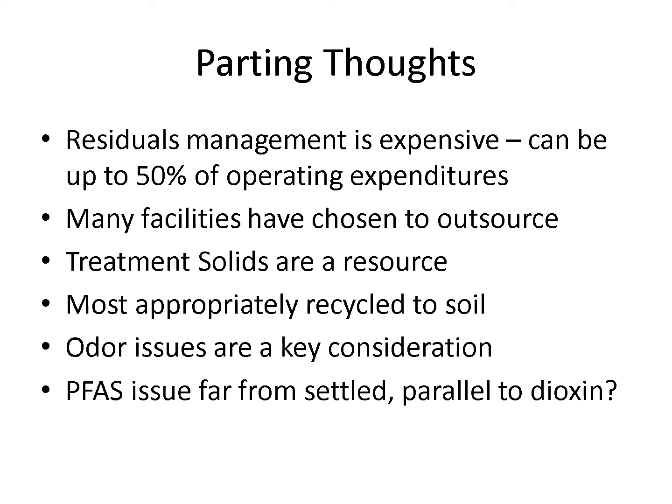One of the things that looks promising is some of the new belt dryers that are on the market. Those will get solids up to about 90–95% solids. And as you'll see in some of the mathematical exercises that we've included, the amount of water in your biosolids is very critical to their final destination and what you do. And they certainly greatly impact costs for hauling. So the better you can do at removing water, the more alternatives you have.